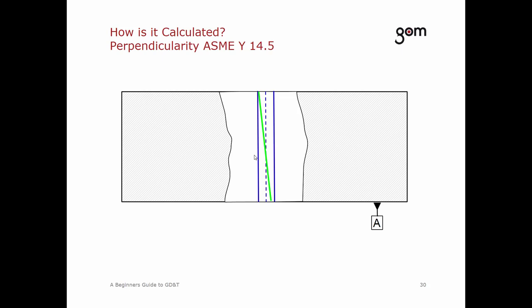So whilst the ISO also takes the form of the element into account, the ASME computes on a straight axis. And this is just one difference in computation. You can find out more about the computation of the standards in the direct help of the software. So that was just the explanation for computation, also the explanation for different results you can have in the software. And let's continue with our fourth concept, the location.